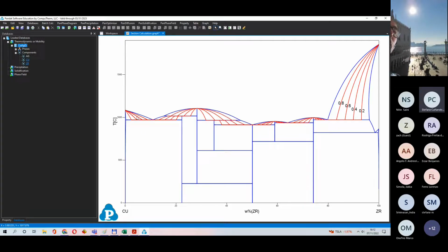We can do the same game here, here, and here. We can do and see the different situation looking at solidification curves in this program. Solidification curves, for the moment, we will use the equilibrium properties. So we will just run a simple simulation, assuming that we have the same rules, so just the thermodynamic rules in solidification like we have in this phase diagram.